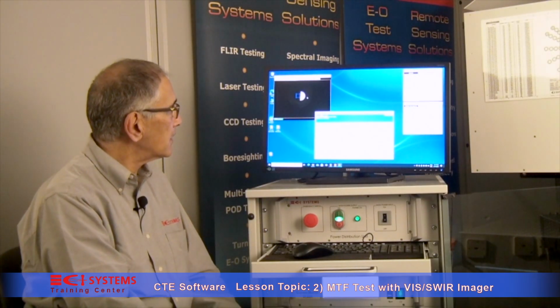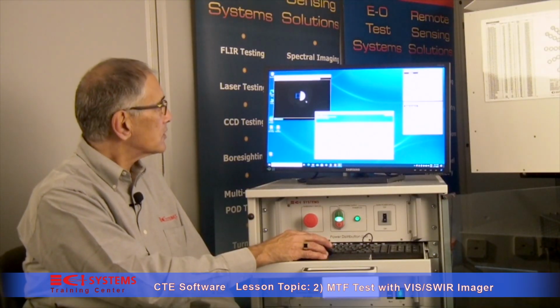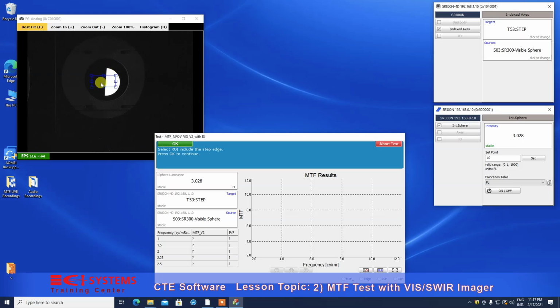It's not in focus. Thermally, it's not the same temperature if we're using an IR source. So just make sure that whenever you're using a region of interest, or whenever it prompts you for a background, it should be within the field of view of the collimator.